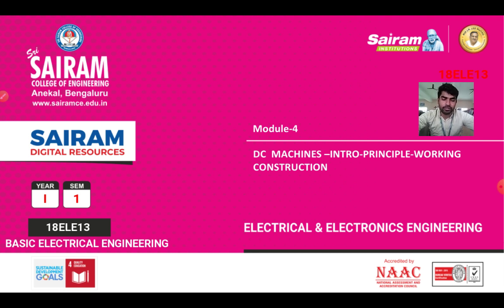Then shunt generator and series generator. The series generator is for welding generators and arc lamps. The shunt generator is for electroplating, electroforming and charging purposes. The compound motor is a combination of both, okay? And I told you the principles: Faraday's laws of electromagnetic induction, Fleming's right hand rule for the generator, left hand rule for the motor, dynamically induced EMF, Lenz's law and all. Working and construction we will see one by one now, okay?